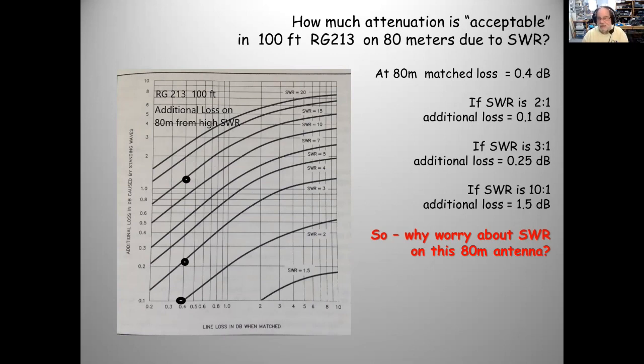How about 2 meters? Yes, yikes, of course. How about 440? Oh, absolutely. But at a low frequency like 80 meters, my coax, RG213, has such a low loss, it's not worth fixing my antenna. A lot of articles in radio magazines talk about how to broadband 80-meter antennas. Oh, give it up. You don't have to, as long as your radio can deliver power.